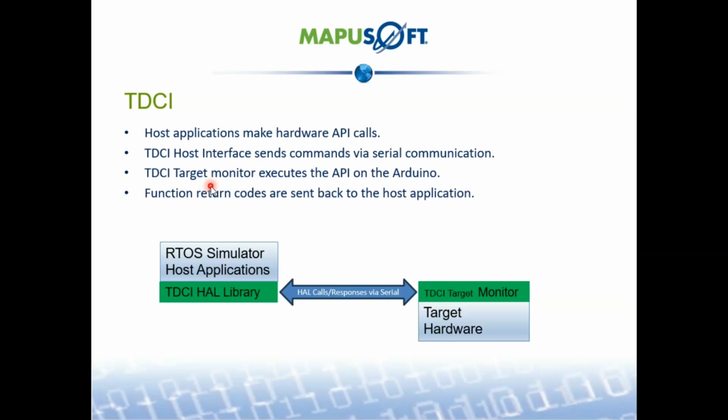The host system sets the predefined humidity threshold value and receives real-time sensor data from the Cortex board. The Cortex continuously reads the humidity level from the HR202 humidity sensor and checks it against the safe range.